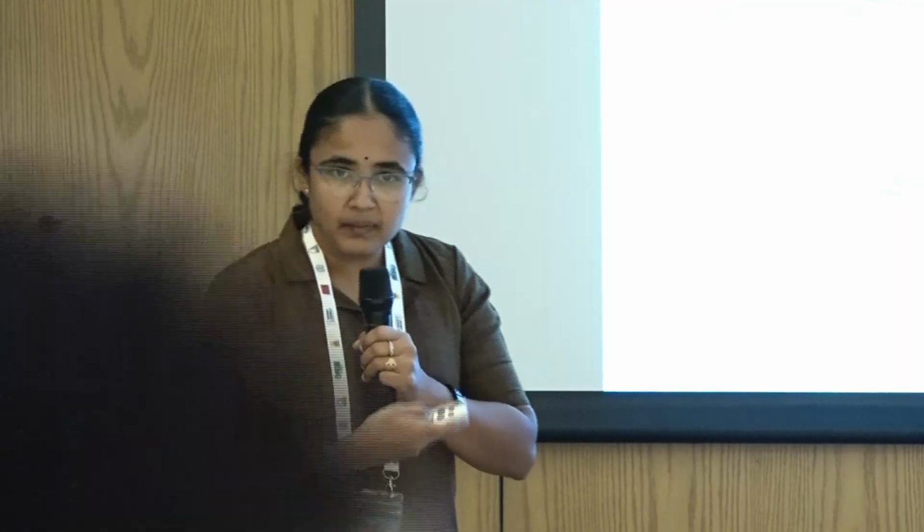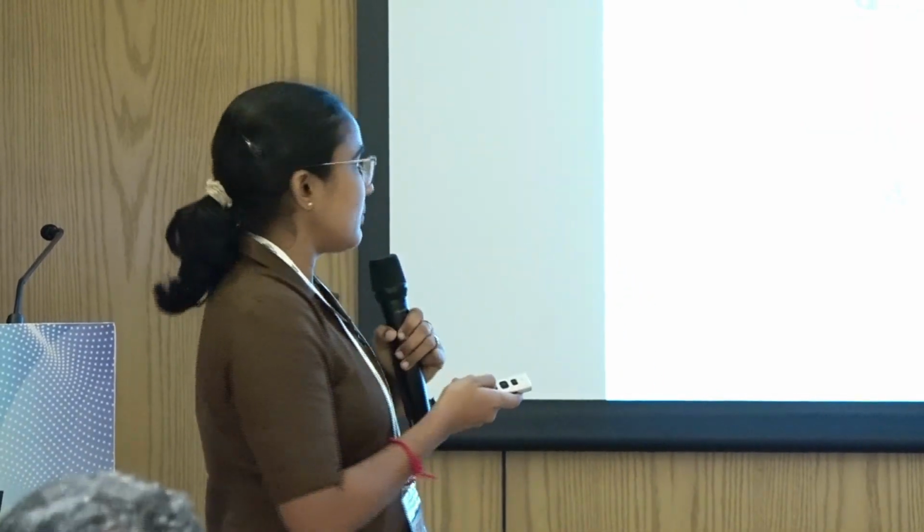When it is under a saturated condition, in the durability analysis we did, even though I have not included it here, it was not passing through all 12 wetting drying cycles. This xanthan gum, even though it is providing high strength in as compacted state, did not pass, because whatever binding action it was providing after curing crumbled during the durability process. So this may be suggested as a stabilizing solution only under as compacted condition, which may not be good for saturated conditions, which may sometimes be critical.